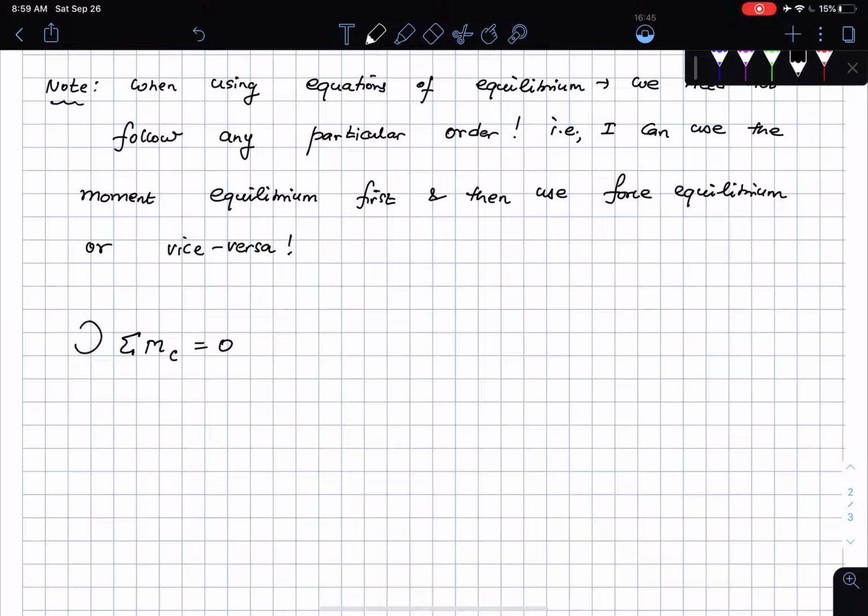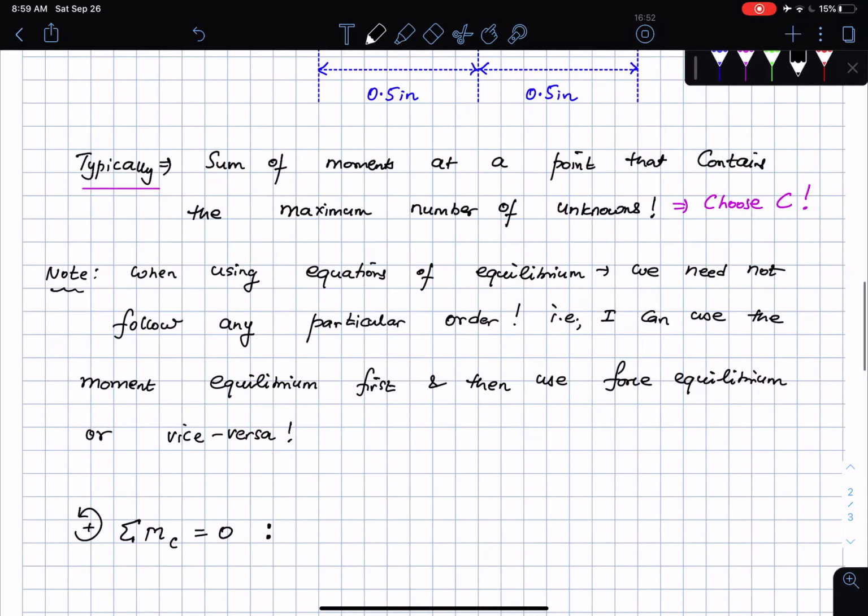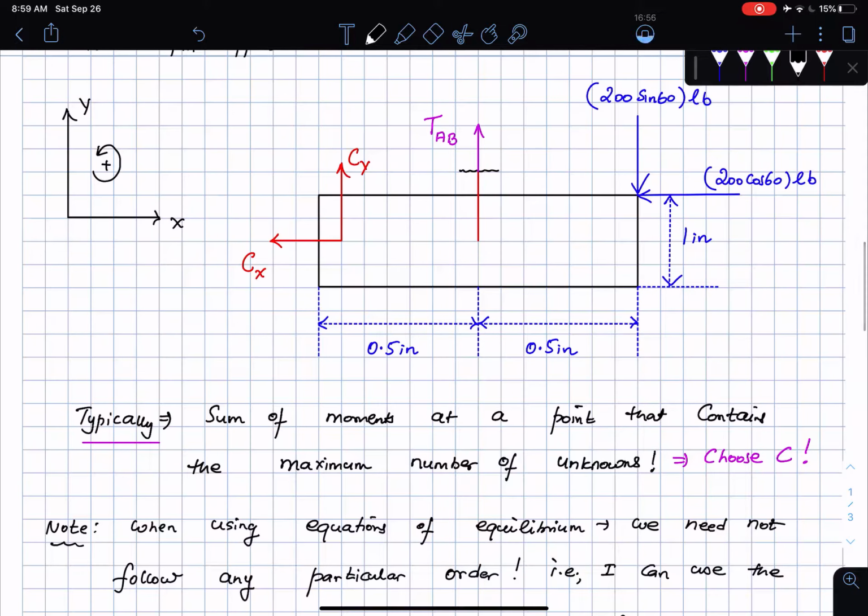All the counterclockwise moments are going to be positive from now on. Please do not forget the 0. Please do not forget the counterclockwise sign. Start off by looking at the figure. Cx and Cy are knocked out of the picture. TAB, right hand rule. What is the distance?